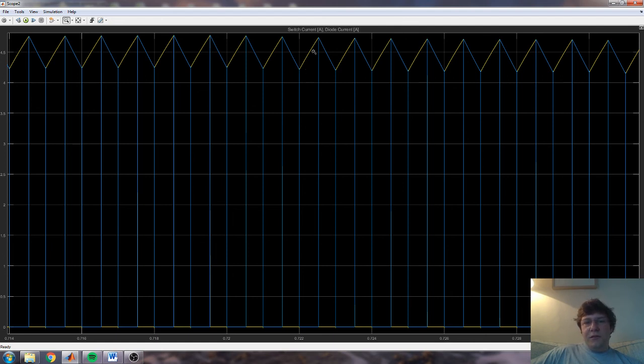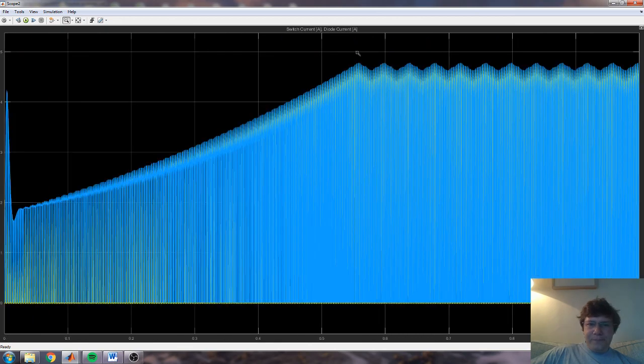We have the charging up of the inductance, or rather the increasing magnetic flux density around the inductor, and then we have the switch switching off and the inductor magnetic field starting to collapse and the energy being transformed into a current driven by the back EMF which is produced, and that switches on the diode and the diode conducts, and we have the current in the diode, and then the cycle repeats over and over.